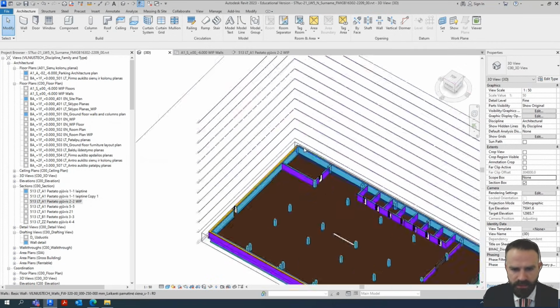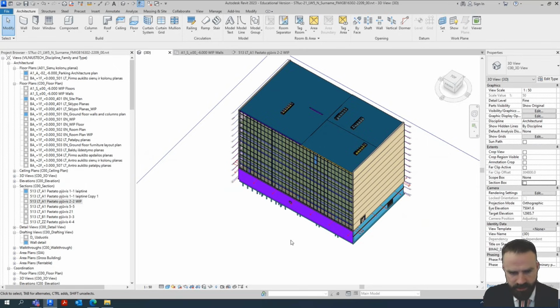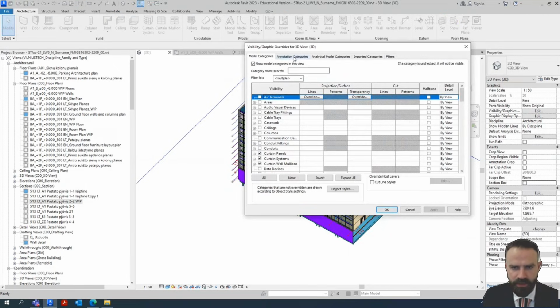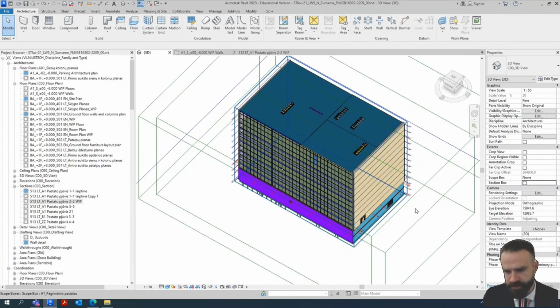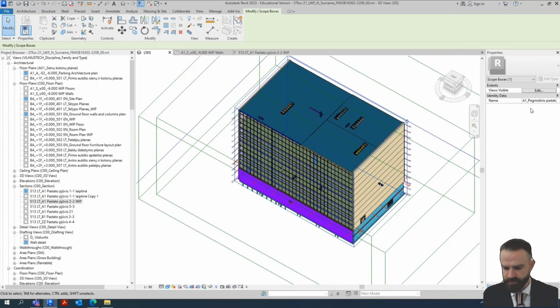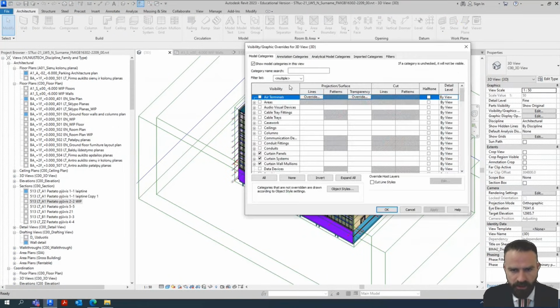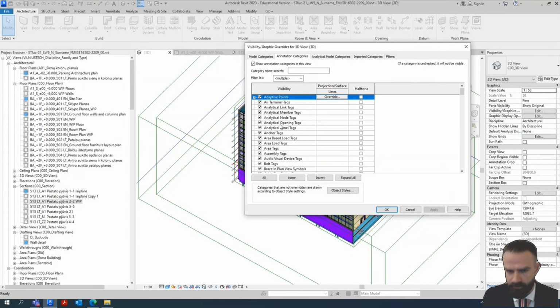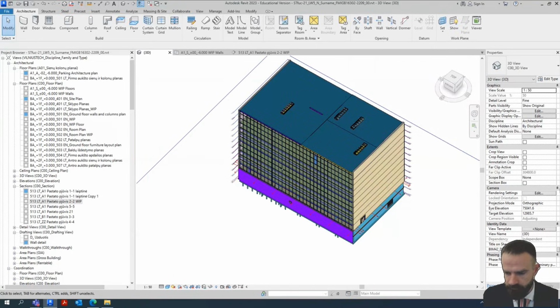And for this section, I select main building as my section view. And also I can change the scope box name, so it is in English. So go to visibility graphics, select scope box, and change the name of the scope box. So the name of the scope box will be main building. And it automatically updates all other views, and now I will have English name for the scope box. Main building, apply.